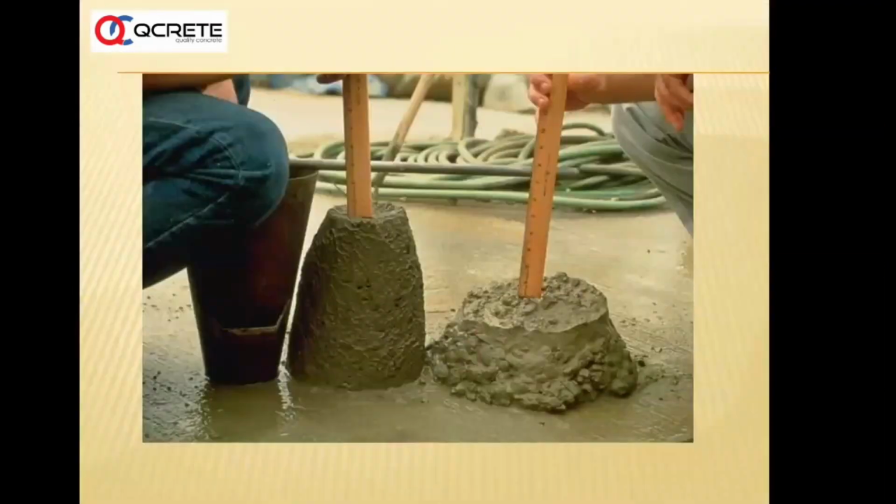Then you have the slump test actually, and when you are making concrete, the mix has to be cohesive. So you can check when the concrete has been produced and it has reached your site, whether the concrete is cohesive. In the earlier days, in the 1990s to 2000, we used to tell, and now also we talk like this, it has to be like curd rice. If you take some concrete on hand and squeeze, the water should not separate, and then it can be pumpable actually.